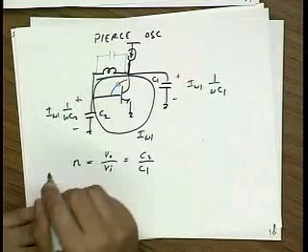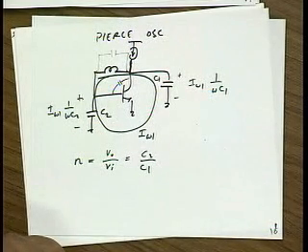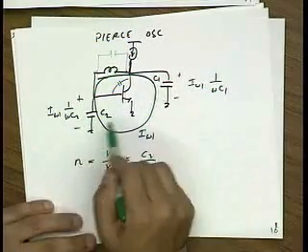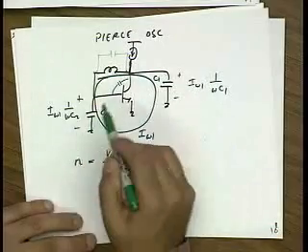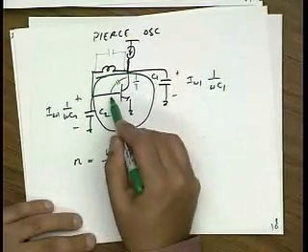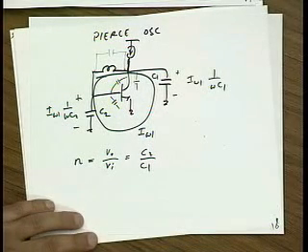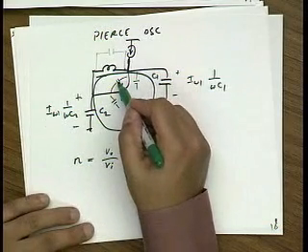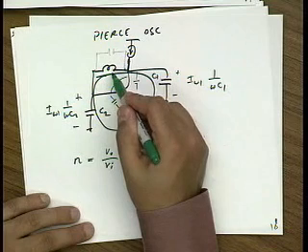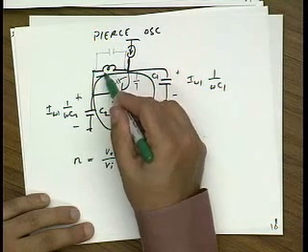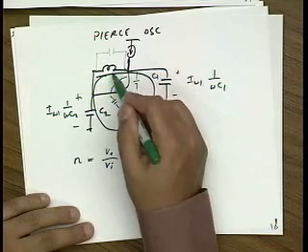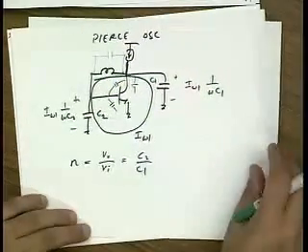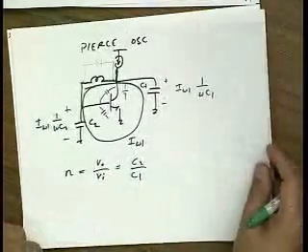So you have some Miller cap. C1 and C2 actually, because they're forming the tank, need to be large enough to pretty much dominate over all the parasitic capacitances in the device. The effect of the Miller cap is not so bad, because what it does is you can think of this cap in parallel with this inductance, right? So if the inductance dominates, basically this cap just changes the value of the inductor a little bit. Do you see what I mean? Change varies over the cycle because the voltage changes on the collector.